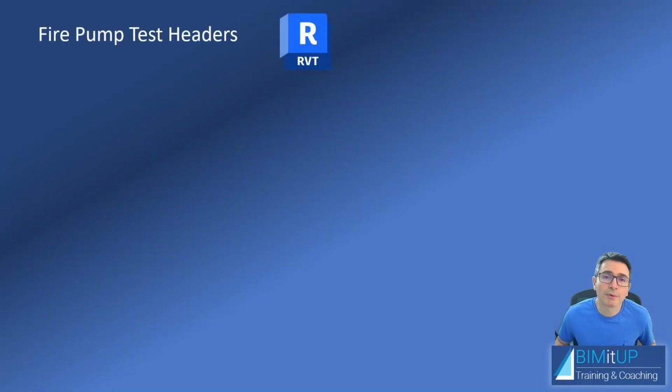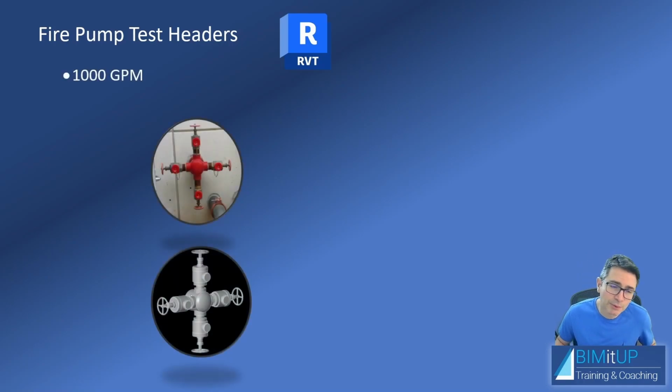Today I'm going to show you how to create fire pump test headers in Revit. Fire pump test headers are used to test fire pumps, and they're typically outside of the fire pump room. The number of fire hose valves depends on the flow of the fire pump. Typically it is 250 GPM per fire hose valve. So for a 1000 GPM pump, you'll require 4 fire hose valves.